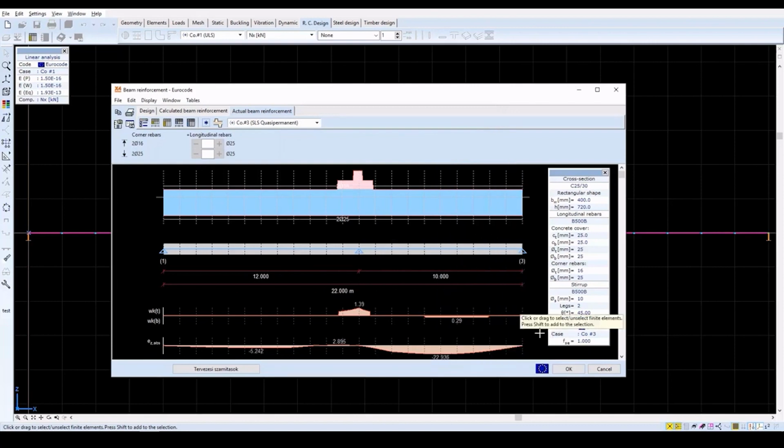The results for deflection are an approximation, since creep is calculated without considering the effect of shrinkage. A more accurate calculation can be made by nonlinear static analysis, which won't be covered in this video. A detailed description of how to compute a nonlinear static analysis can be found in the PDF Beam Model Tutorial Guide on the AXISVM website.